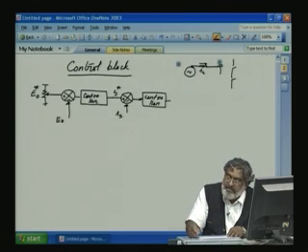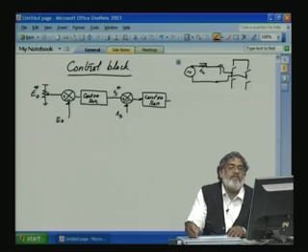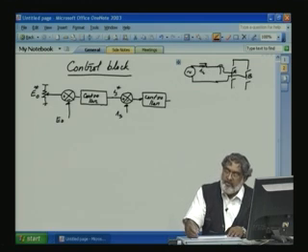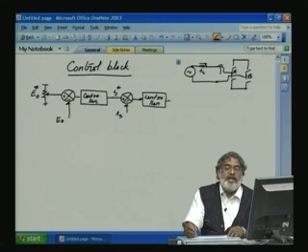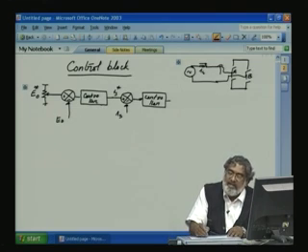what is required is the fundamental component of VAB with the PWM. It should be the required VAB or reference value. So, the reference value for VAB is the output from here. So, this will go to the VR reference.